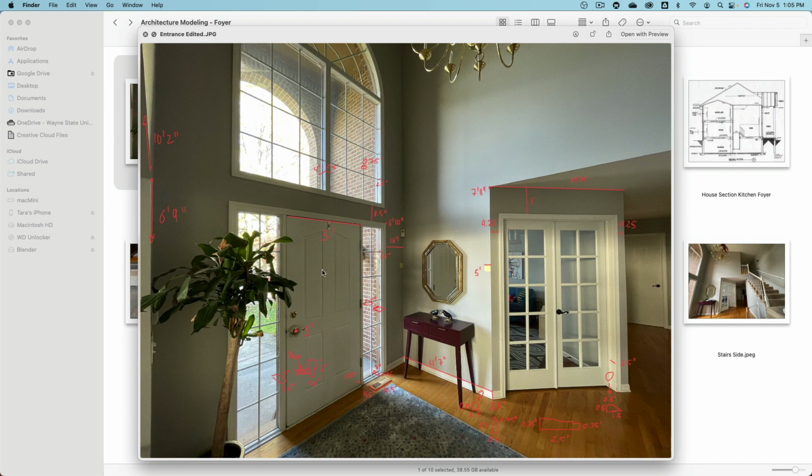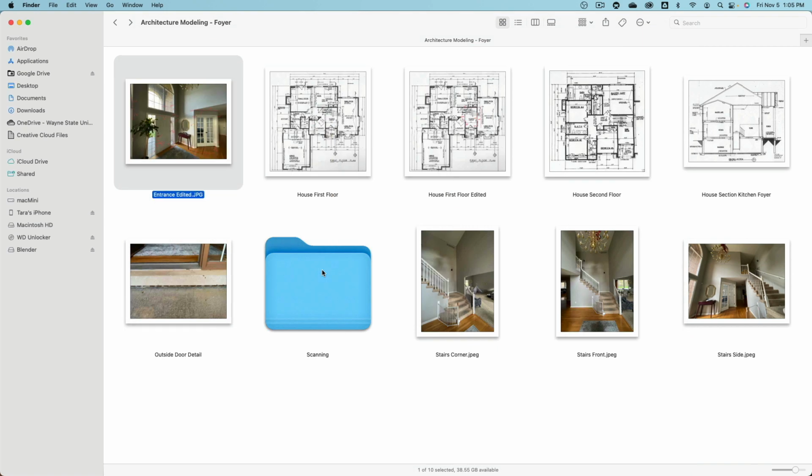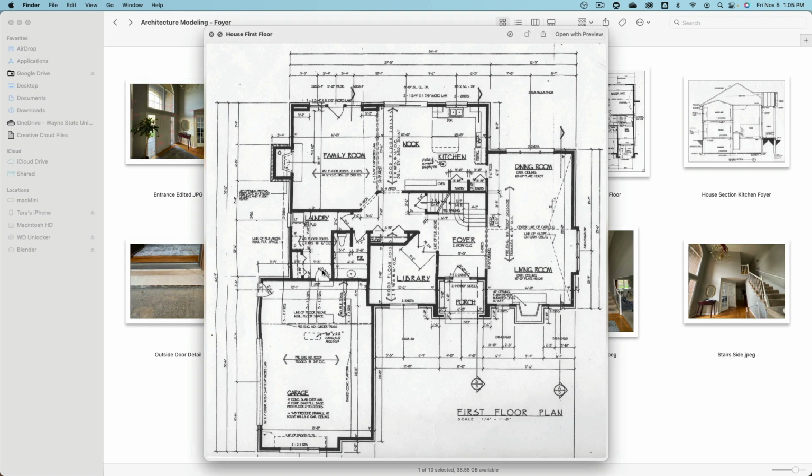Okay, cool. The other option we can do is we can look for construction drawings from the city, the construction company, or the architecture company. These drawings, for example, are 30 years old. And with these drawings, there are two common problems. First, the drawing you see here, is this really representing the final result? Or are these the drawings before construction?